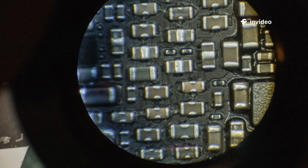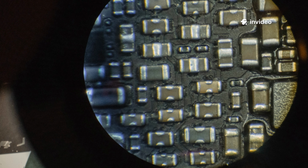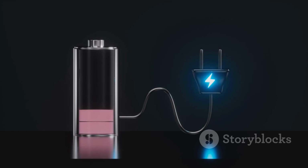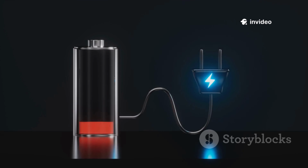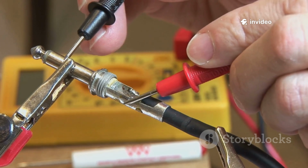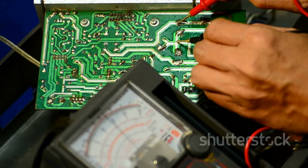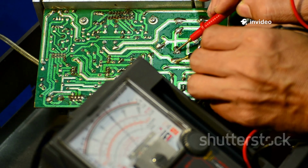Each resistor placed in parallel provides a separate path for the current, effectively reducing the overall resistance of the circuit, and all the branches eventually meet up again, converging before returning to the original power source, completing the circuit. The total current is divided among the various branches, with each branch carrying a portion of the total current. But here's a crucial point. The voltage across each branch in a parallel circuit remains constant and stays the same.